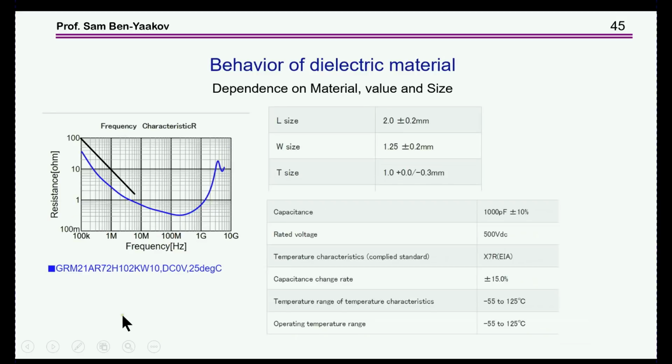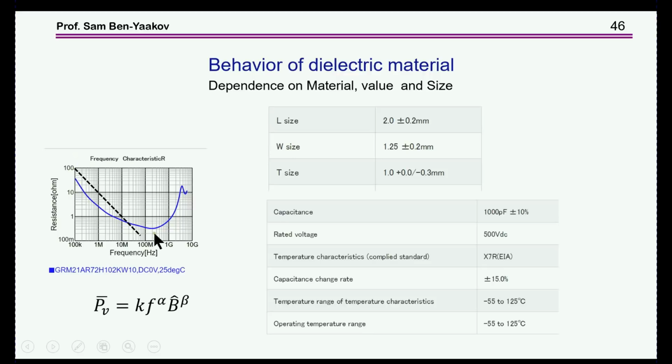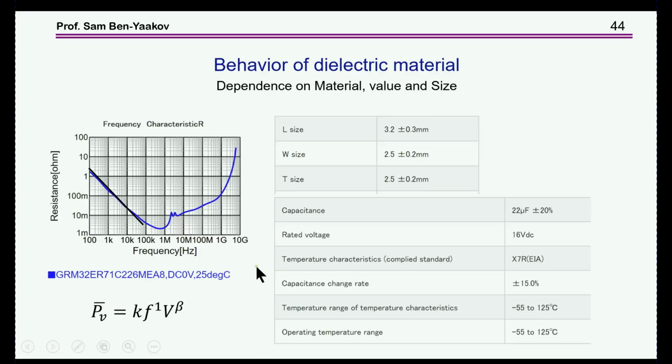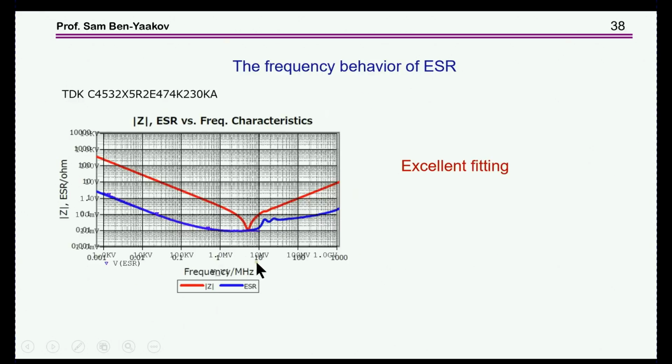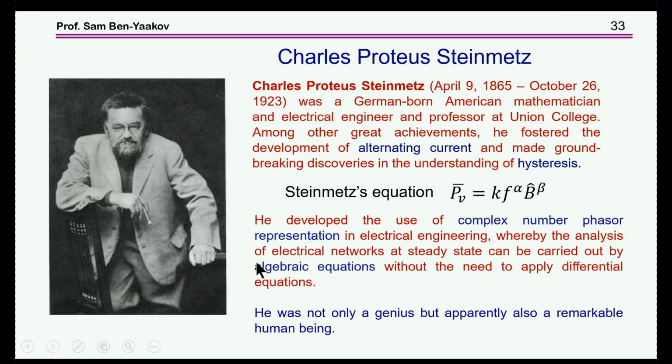In some capacitors, it's not, meaning that if you'd like to describe the losses as a function of this nature, like in the ferromagnetic material, you'll have to have some other constants, alpha or beta, as we do today. Let me go back just to stress this thing. Steinmetz put here fixed numbers.